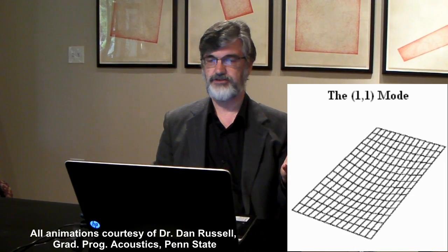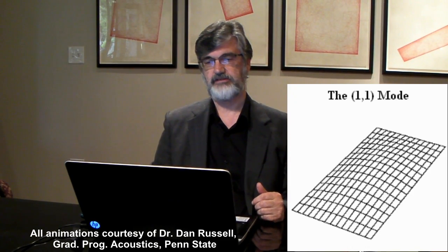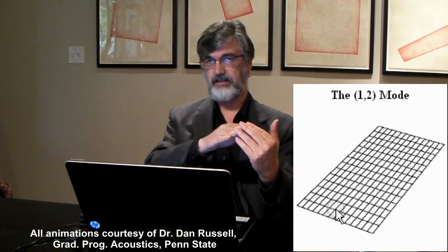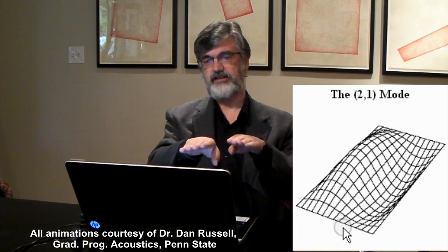So now if we go to the animated slide that shows these modes, you'll see that in the very first mode, the primary mode is what you want. All of the plane is moving forwards and backwards at the same time. The next mode goes into front to back, where half of it's moving in, half of it's moving out, but this is damped in our case. The next is when they move side to side, and then finally in the last mode it's divided up into 4 pieces where 2 corners are going up while the opposite 2 corners are going down.